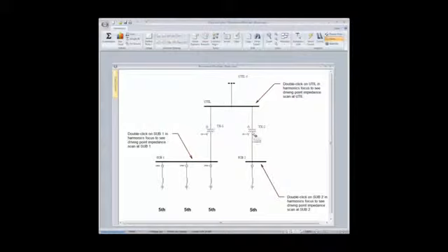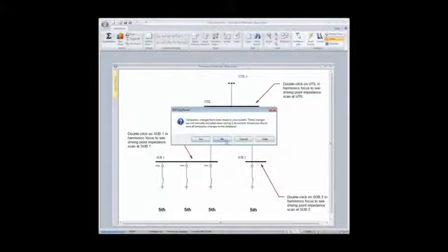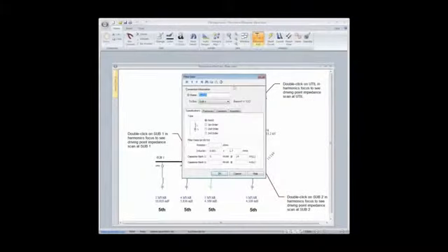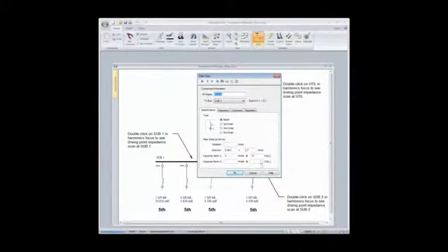The next key item when you're looking at the notch harmonic filter is going to be capacitor duty. And John, it's really interesting that you're on here, and we had discussions about this just last week, how applying the capacitor standard 18. Now, if we go back to the database focus, and we look at the notch harmonic filter, which has been selected here, notice that we have two key components that we're looking at. We're going to be looking at the inline reactor, a series reactor, and a capacitor.